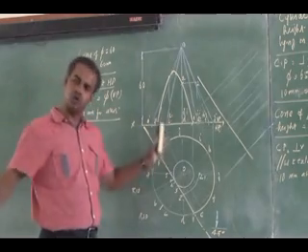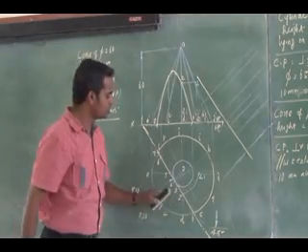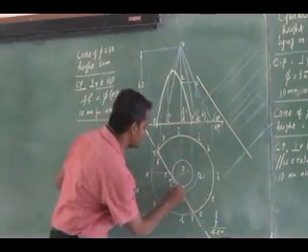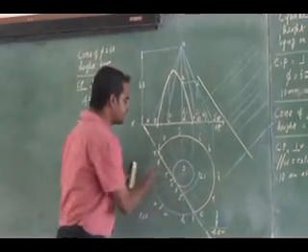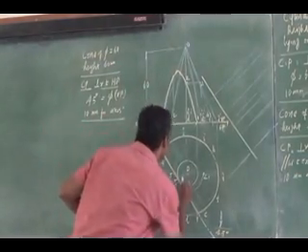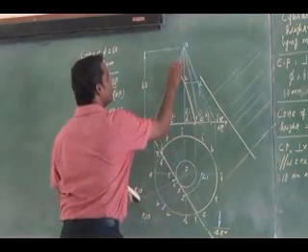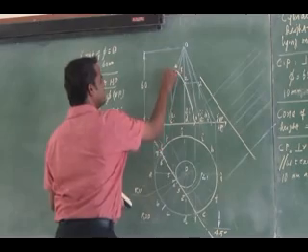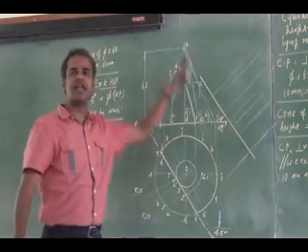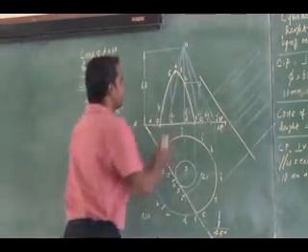You are getting 6 points, right? No problem. So I have here 1, 2, 3. Cutting point 3 is on OC. OC can be projected directly. These are all slant generators, so these cutting points are directly projected. This is my 3. This is my 4. This is my 5 extreme. This is going to be my 6. Then 7. By joining this with a curve and a straight line, I will have my section.